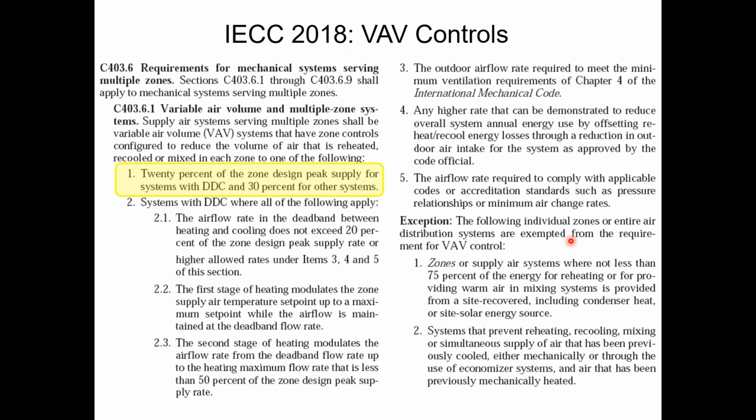Now, some electronics are for outdoor use and some are not. So for example, the circuit boards that we use in our packaged rooftop units have an epoxy coating on them, which makes them more resistant to humidity and stuff like that. Whereas the ones used in most VAV controllers probably don't have that because they weren't really designed to go outside.